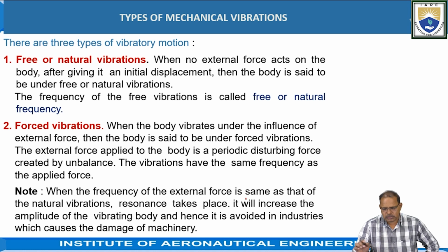When the frequency of the external force is the same as the natural frequency, resonance takes place. It will increase the amplitude of the vibrating body. At the same time, it also gives noise, which causes damage to the parts which are moving relative to each other.